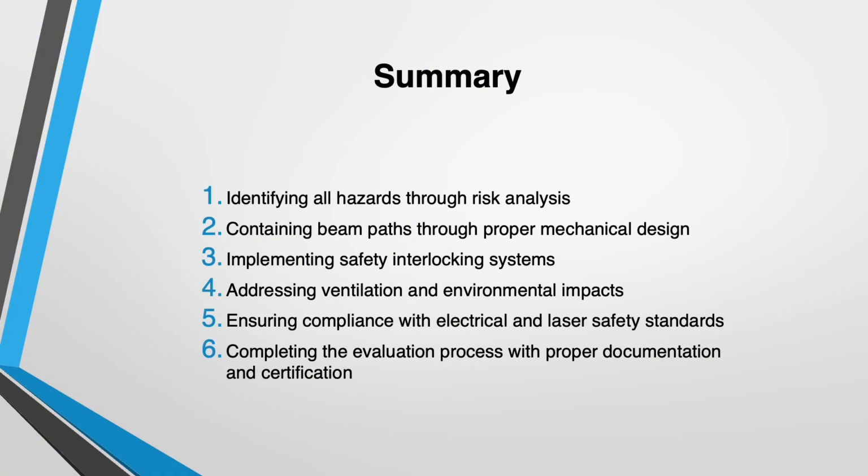In summary, laser safety requires a comprehensive approach that includes identifying all hazards through risk analysis, containing beam paths through proper mechanical design, completing safety interlocking systems, addressing ventilation and environmental impacts, ensuring compliance with electrical and laser safety standards, and completing the evaluation process with proper documentation and certification.